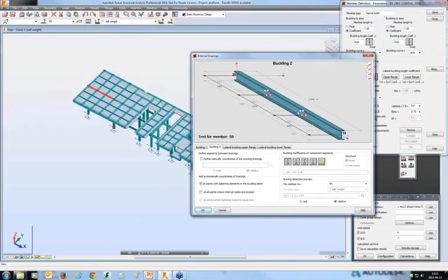There are two beams in the horizontal direction, which is correct. That's buckling Z restraint, lateral buckling for the upper flange. Again, we have these two secondary beams. And for buckling for the lower flange, we have one restraint at the beginning and one, let's say, in 1/4 of the element length, which is supposed to correspond to the bending moments from self-weight.